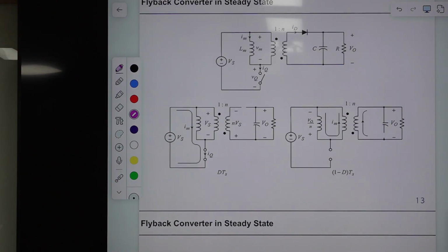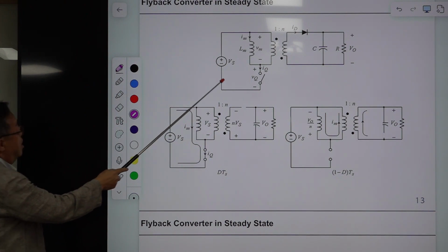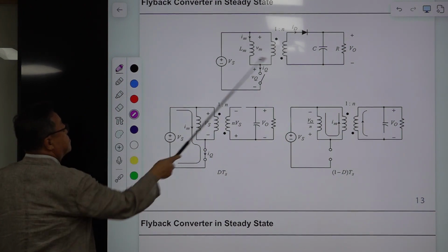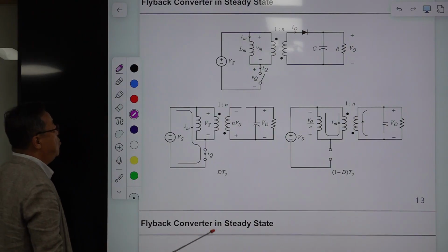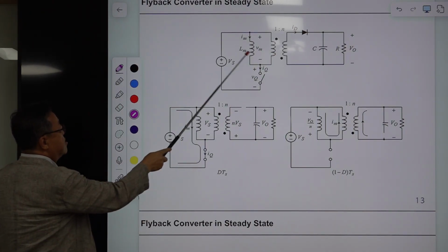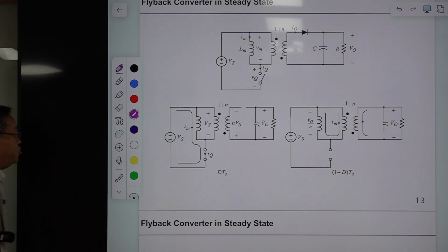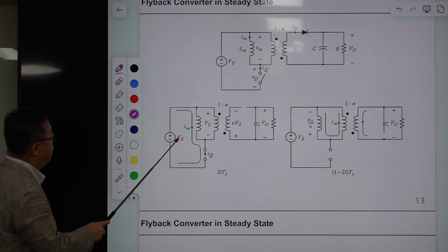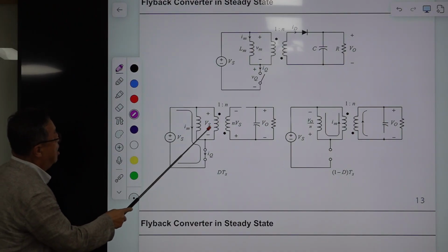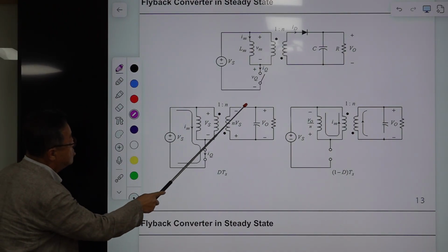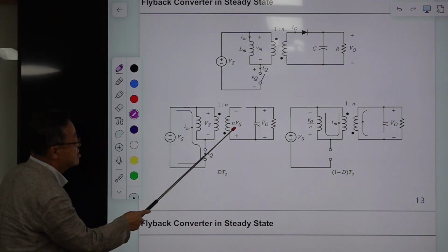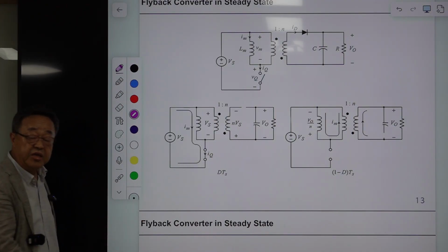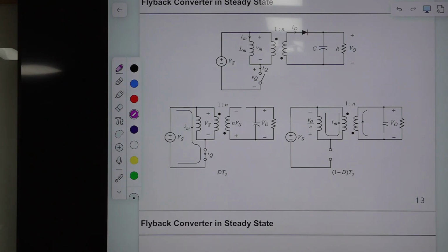All right. So this is the rearranged circuit diagram, and this is the flyback transformer, ideal transformer, and this magnetizing inductance. This is the MOSFET switch. During the on-time period, this is turned on. Then Vs is applied here. Because of this, regardless of the connection of this, the N Vs will be developed by the equation of the ideal transformer. Then there was a diode here.